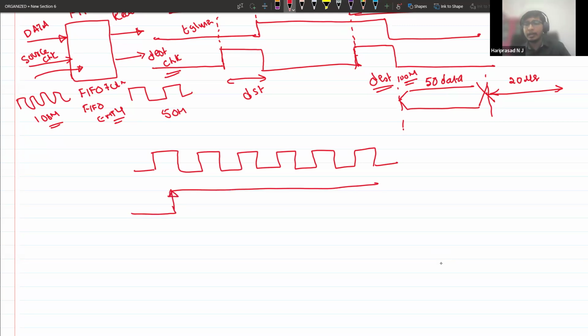So what is the logic generally used for identifying the positive edge of the data? These are three important things in synchronization. One is toggle synchronization, where you keep identifying the toggling part using XOR, because it identifies the positive edge or negative edge. It basically toggles and generates the pulse.